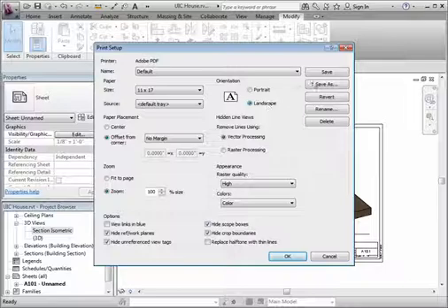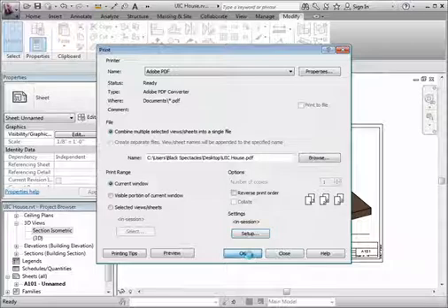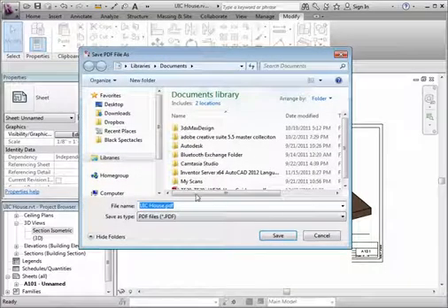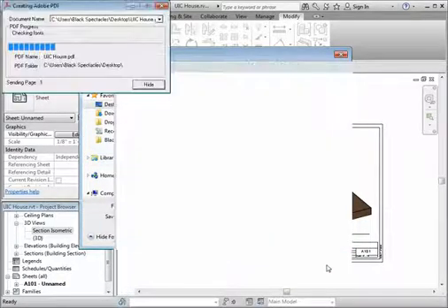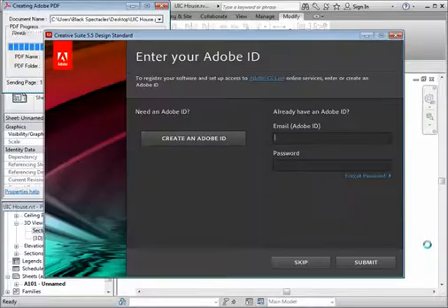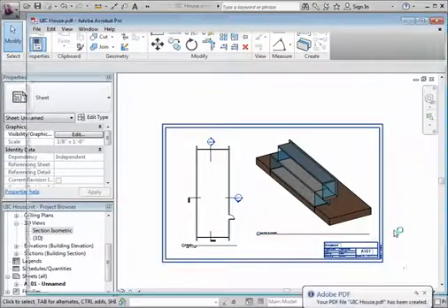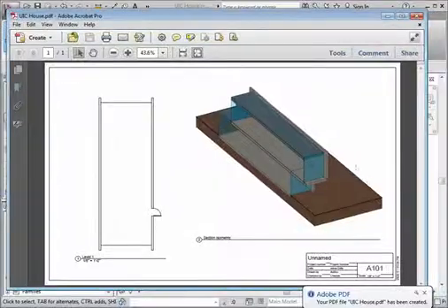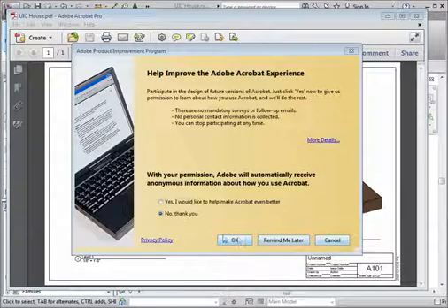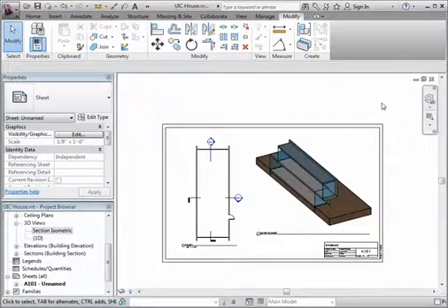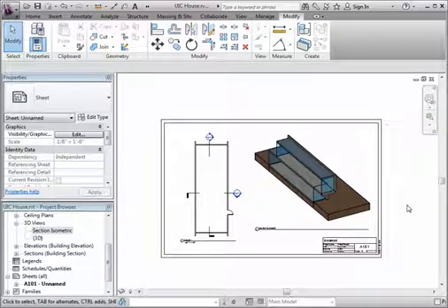You could save these settings as, and then use them over and over again, and then just click OK. And that's fine. It's going to use what's best. Desktop, save it as. And there you go. So that's printing. So that's just kind of taking your round trip of making something really simple in Revit. How do you get it on a sheet? How do you print it?